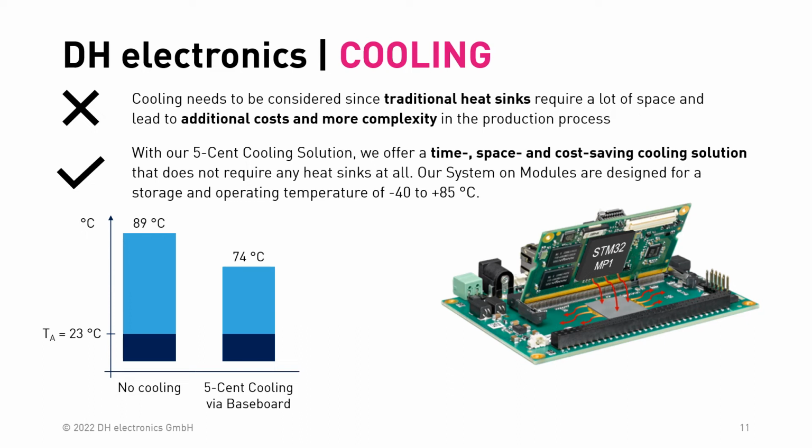We have done a test in a closed box, and we started a stress test on the STM32MP1, and with an ambient temperature of 23 degrees, the CPU gets 89 degrees hot. Only by adding this simple gap pad, we can reduce the heat to 74 degrees.